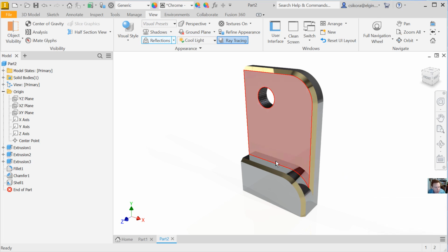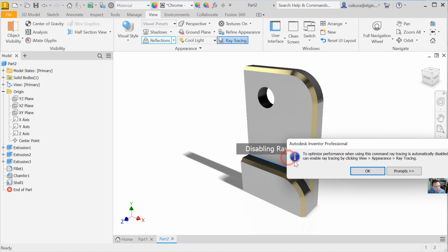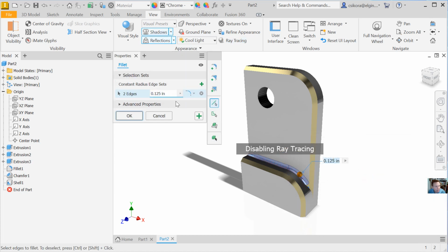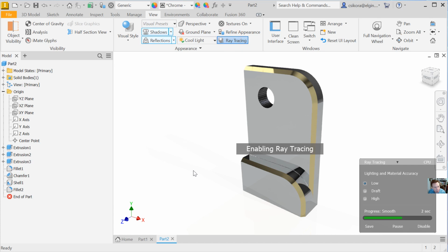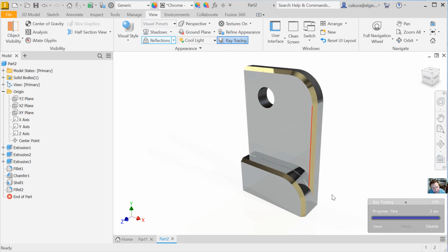Now you might notice that it goes flush here, especially with chromes and such. A little trick, and I think it's probably in there, but I haven't found it. Some systems have the ability to select an edge, and you could put a little broken edge on there. I'm going to break that edge 0.01, so 10,000ths of an inch. And now when we render it, it looks a little bit more realistic because now that edge is broken like it would be in real life, because it would be near impossible to get it that close. And you could break other edges too. That's a manual way, but I believe there might be a setting in there. If one of you knows where it is, go ahead and put it down below in the comments.